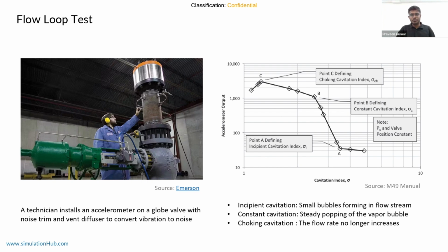And this is the point. Point A is the incipient cavitation index, where small bubble formation has started. And it goes to point B, where you can hear a constant, steady popping or cracking of bubbles, and it's clearly audible.